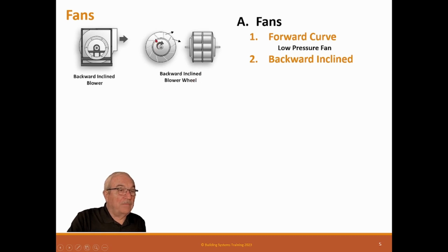The only problem with these is most people look at this and say it's running backwards. They want it to run this way. And it'll push air that way, but not very much. It'll push maybe 10, 15% of its airflow when it's running backwards. But that's something you have to check, because most, including operators, will look at a fan and say, well, that's running backwards. But it's not. It runs pushing. It's paddling that air as it goes by. And these can be low to high pressure fans.